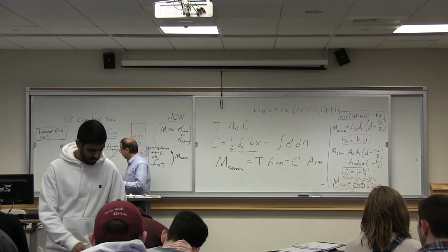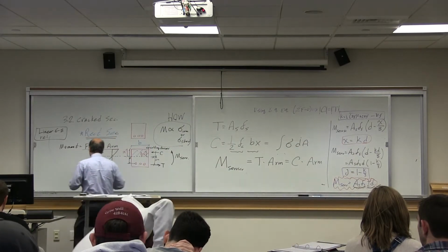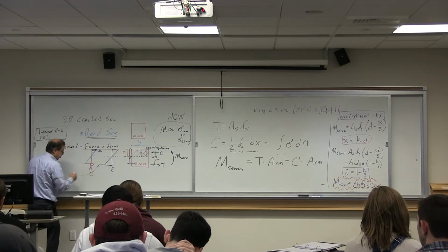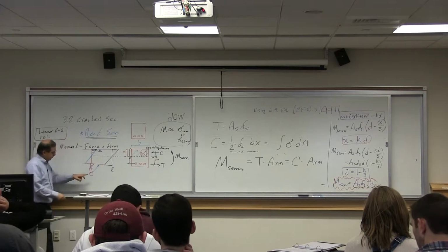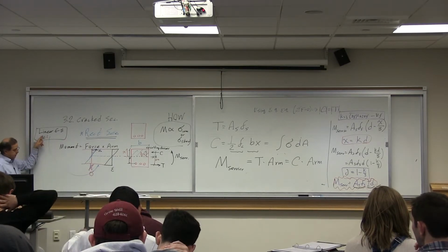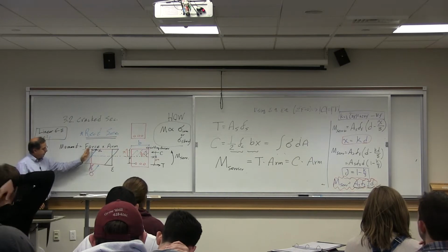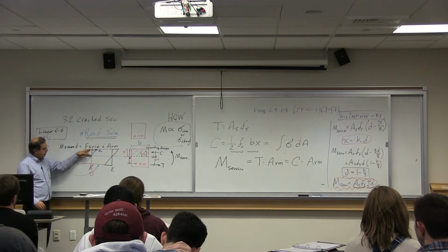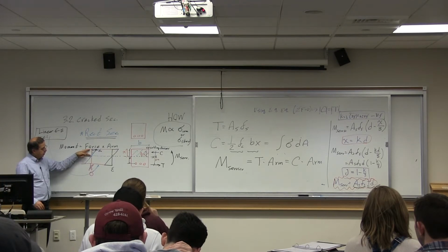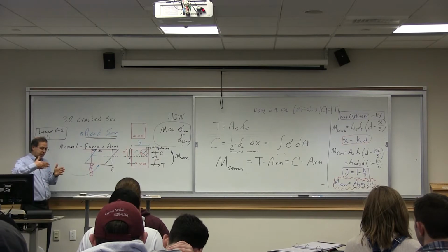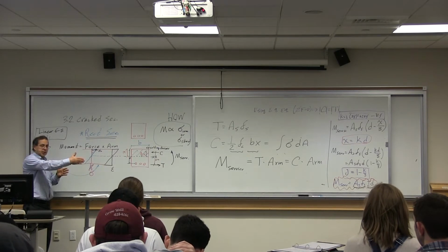The variation of, I'll put here strain, this is incorrect. Please correct this. This is a stress, not a strain. The variation of stress within the section is linear because material properties are linear. So given that the stress variation within the section is linear, and this is a triangular variation, we know this triangular variation is constant across b.